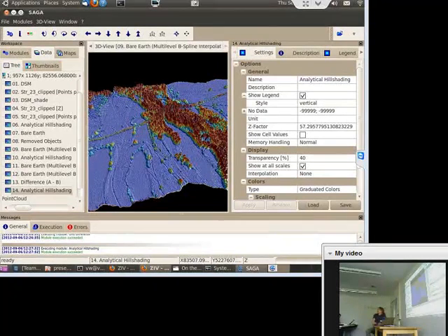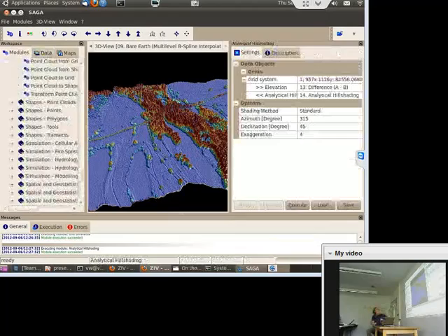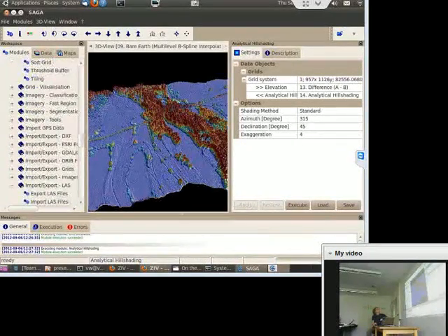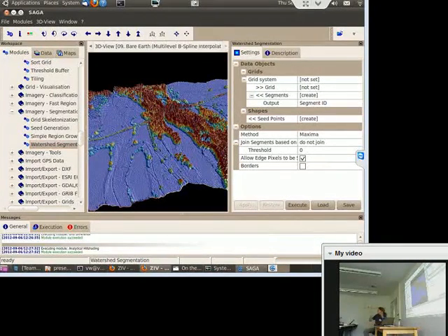For vegetation analysis, you could make a mask for vegetation and would have tree heights, for example. The next step would be to create a vegetation mask, just masking everything to no data except vegetation. And the vegetation should keep its elevation. And then you go to the segmentation module, imagery segmentation, watershed segmentation, put this grid into it, and you get individual trees derived. It detects local maxima, which should be the treetops, and segmentizes like a watershed, and you get the extent of the individual trees.